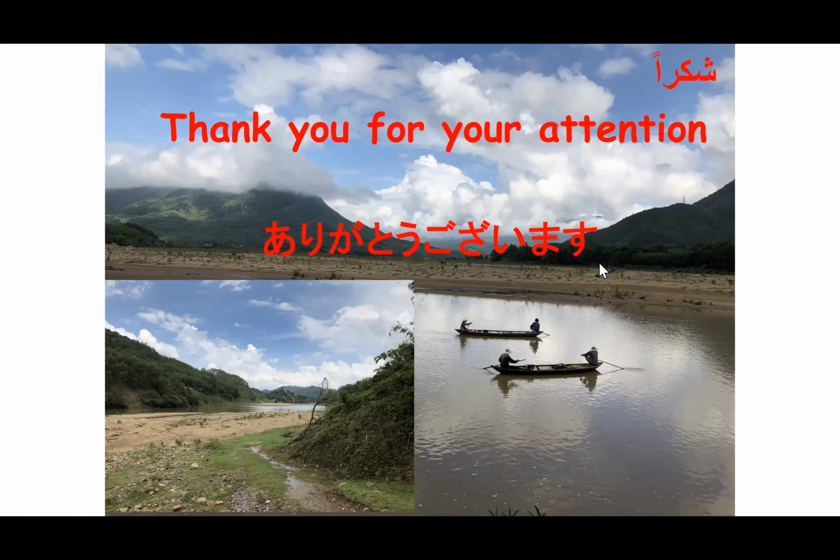So this kind of gabion or concrete stone dam, like a rock-filled dam, you mean? This kind of dam is very small, more than 5 meters or around 6 or 7 meters. Maximum is 10 meters. So these dams are very important for flood management. But as I said, with time, these dams will be filled with sediment.